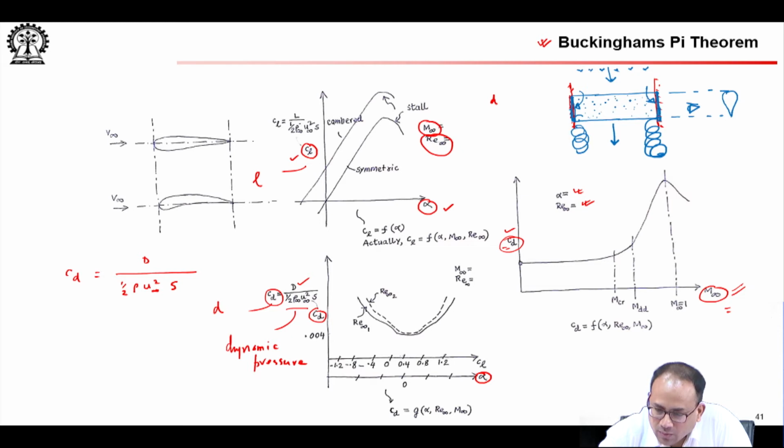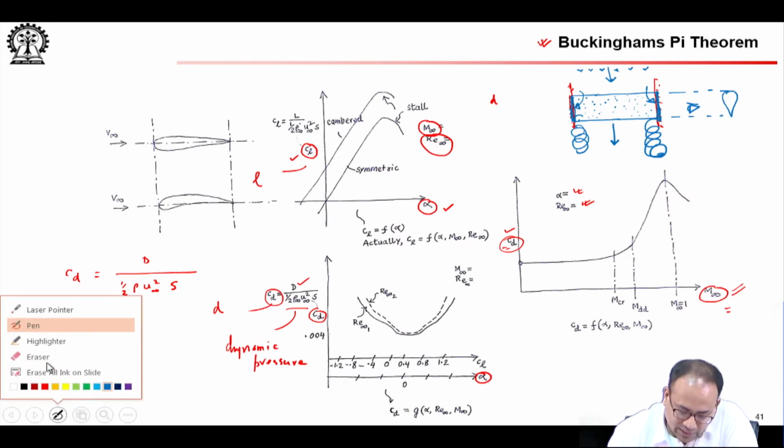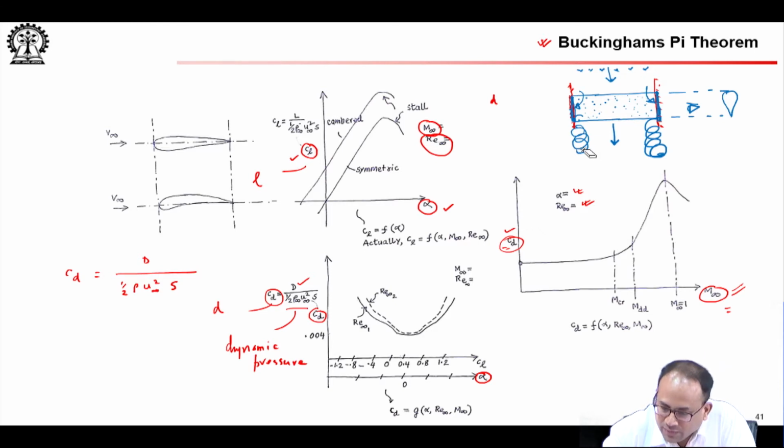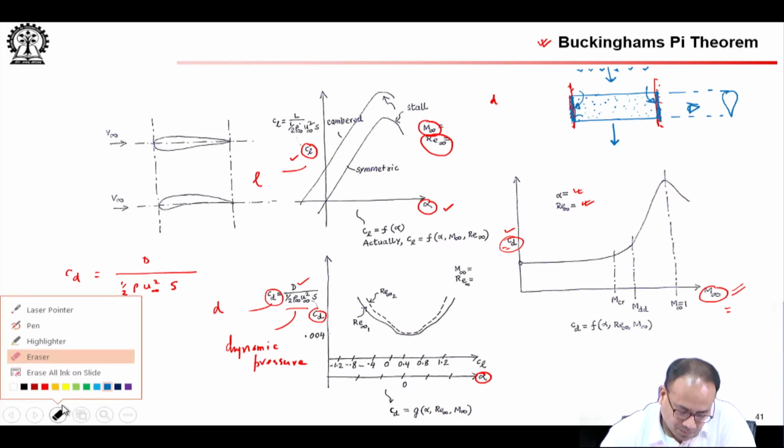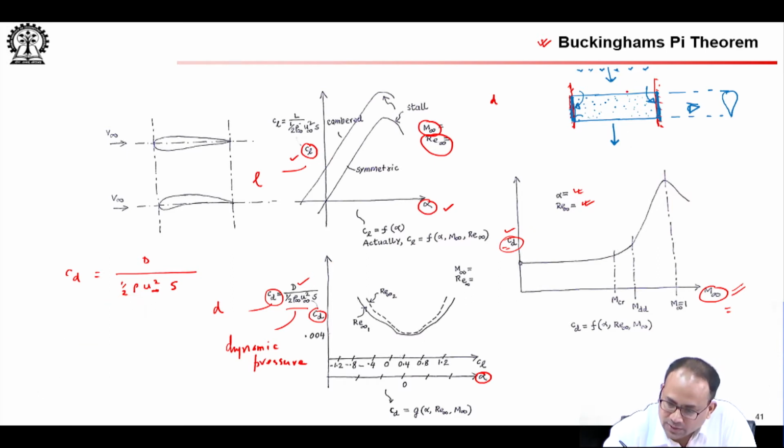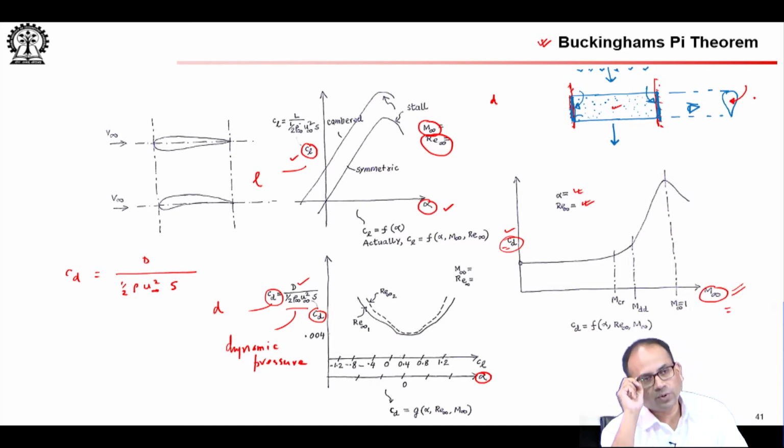Okay. So, you need to make sure that it is flush, and then again you run the visualization and you see that there are no trailing edge vortices, because if you have these trailing edge vortices, you are really running an experiment for a finite wing. Okay. Now, so we put this thing of constant cross section that is of a particular airfoil geometry.